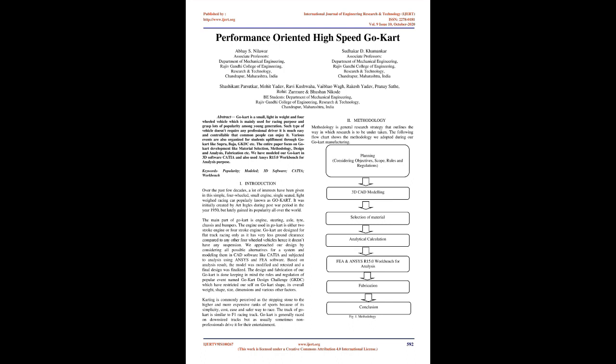We approached our design by considering all possible alternatives for a system and modeling them in CAD software like CATIA, and subjected them to analysis using Ansys and FEA software. Based on the analysis results, the model was modified and retested and a final design was finalized. The design and fabrication of our go-kart is done keeping in mind the rules and regulations of the popular event named Go-Kart Design Challenge, GKDC, which restricts us on go-kart shape, its overall weight, size, dimensions, and various other factors.